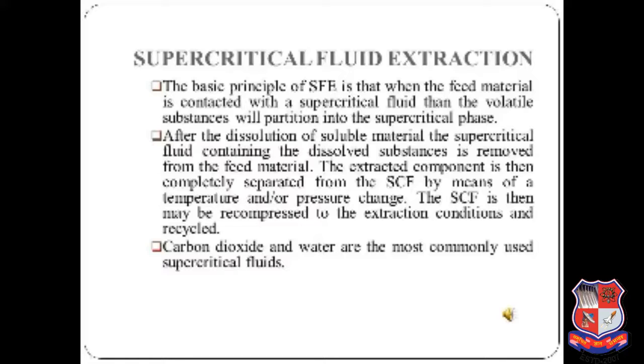be extracted. The dissolved material is swept from the extraction cell into a separator at low pressure and the extracted material is settled out. The CO2 can then be cooled, recompressed and recycled or discharged to the atmosphere. So on this basis the process is going on.